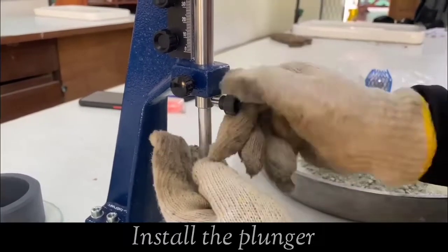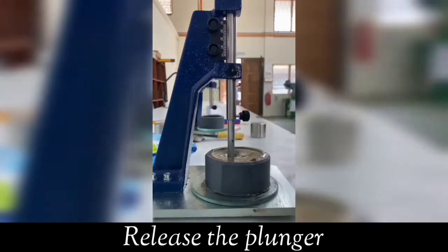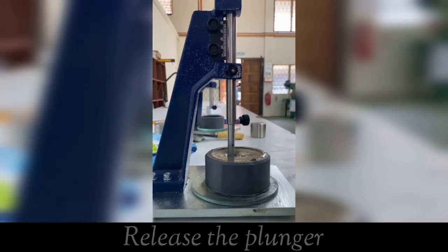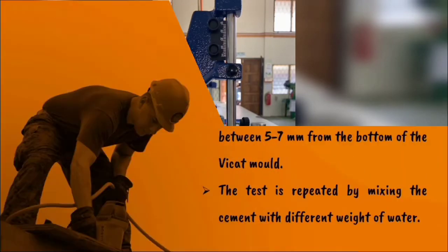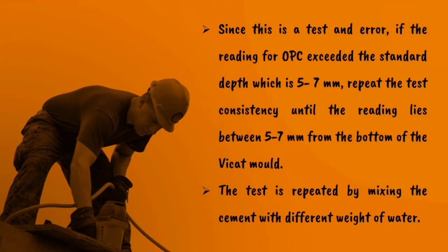Install the plunger and the VICAT mold is placed under the plunger. Then the plunger was released so it penetrates the cement paste inside the VICAT mold. After releasing the plunger, wait for 3 seconds and note down the penetration reading. Since this is a trial and error test, if the reading for OPC exceeded the standard depth of 5 until 7 mm, repeat the consistency test until the reading lies between 5 until 7 mm from the bottom of the VICAT mold. The test is repeated by mixing the cement with different weights of water.